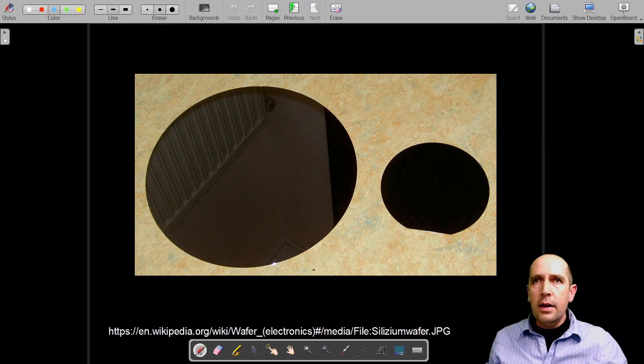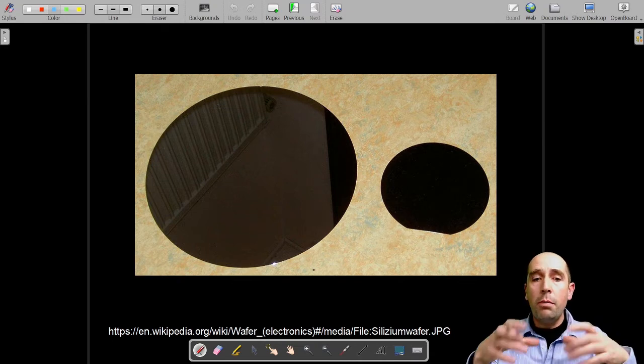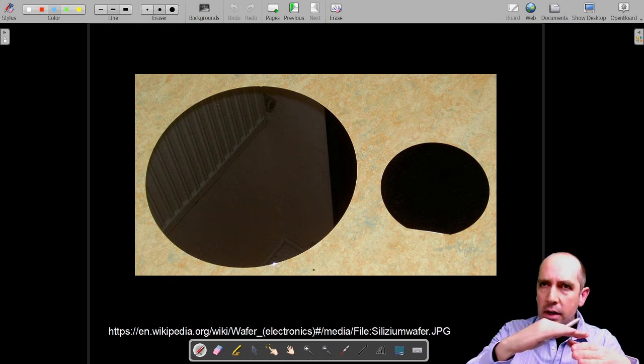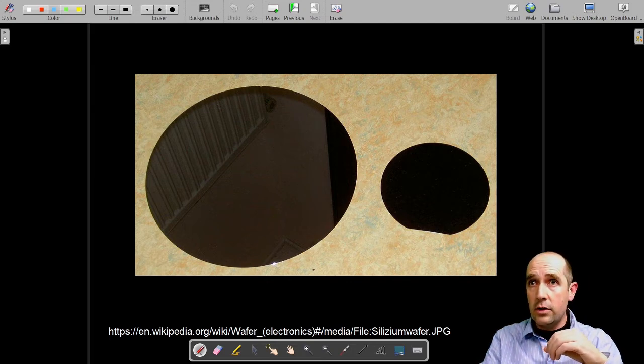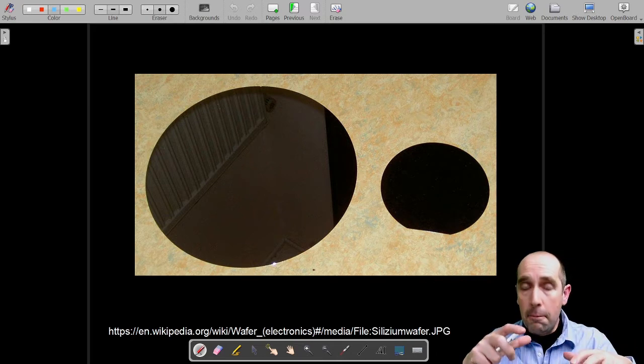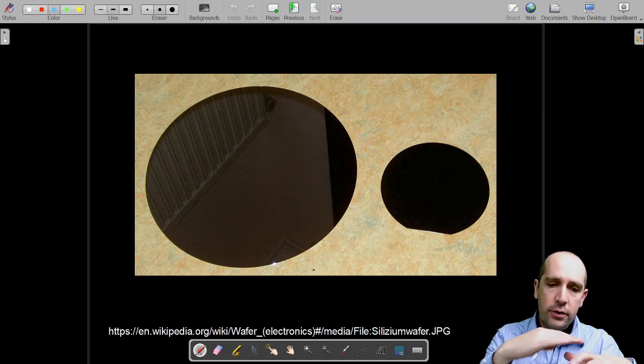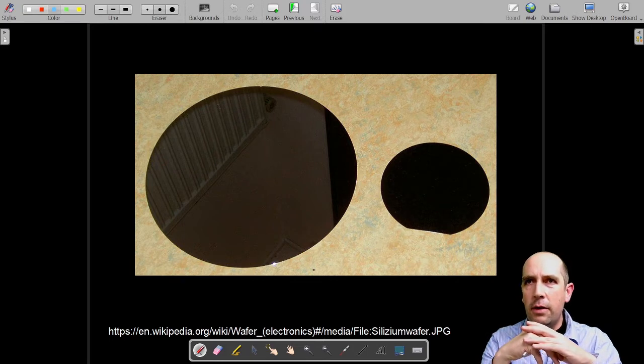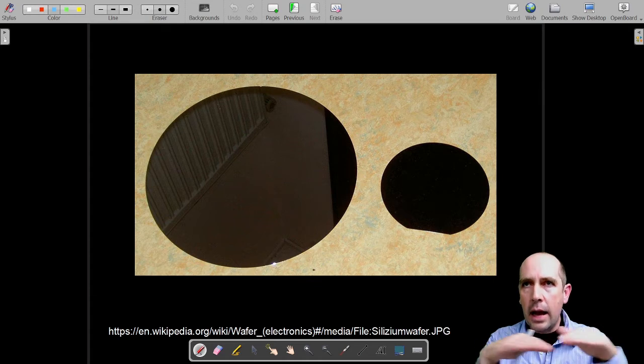They look like this, and essentially on top of these wafers, which are cut very carefully so that one is following one of the crystallographic directions, and therefore the surface is in one of the crystallographic planes. And after sawing, the surface is polished and brought down to a really super flat degree, as much as possible aligned with the crystallographic direction.